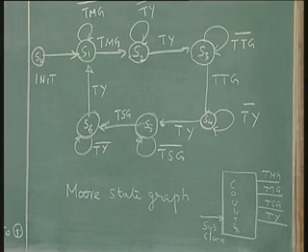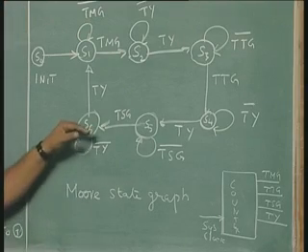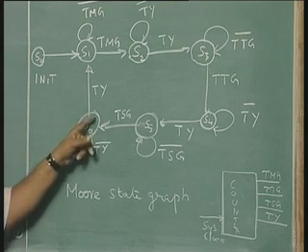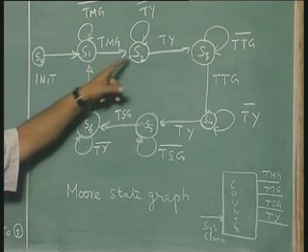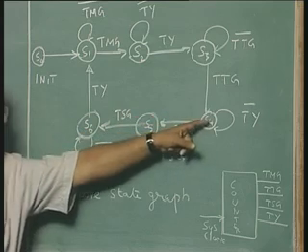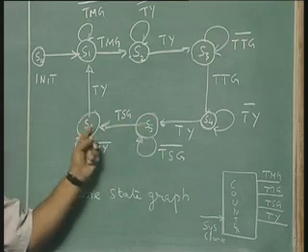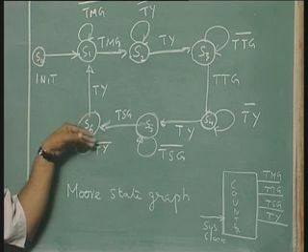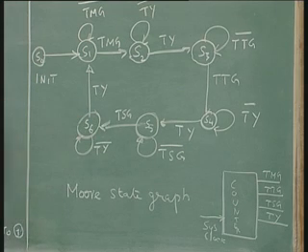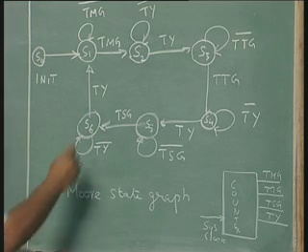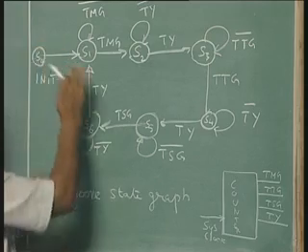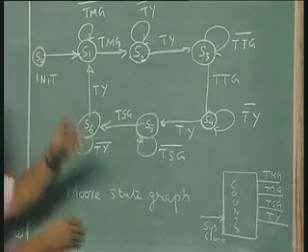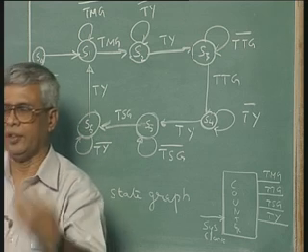Normally in a Moore circuit I should write the outputs in the states, but the state circles are too small, and I have already used them to write the state label. I do not have space to write the whole list of outputs in each state, but we know we have already listed them there. So, this will do. This extra state I have here, do not worry about it. It goes on repeating in 6 states, assuming it goes forever.